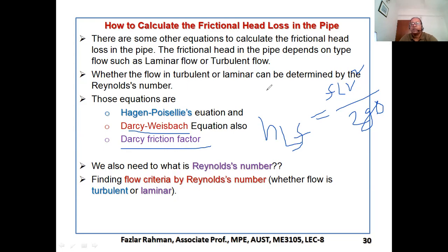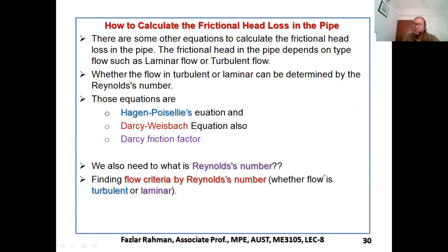Then it depends on the diameter of the pipe, and on how much surface finishing there is in the pipe. Even if you have a glass on top of your table and you put your hand on it, you feel it is smooth. But under a microscope, you might see the surface is not perfectly smooth; there is still some surface roughness. Similarly, you buy a plastic pipe and you feel it is smooth, but actually it is not.